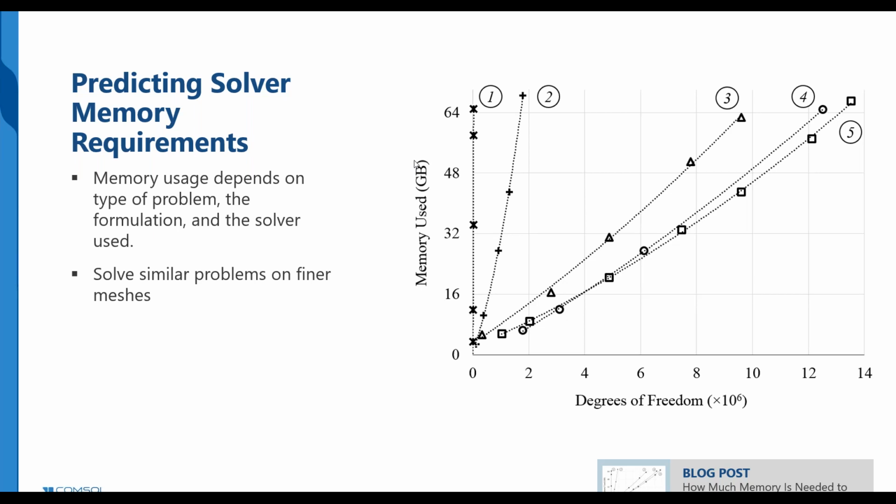When running several instances of COMSOL without specifying the number of cores, will they detect and adapt dynamically the number of cores used? Well, that's a good question. No, they will not do that. When you start COMSOL, it will not consider what else is done on the machine. A common problem is when you're running on a big Linux workstation or any kind of computational server which is shared among different users.